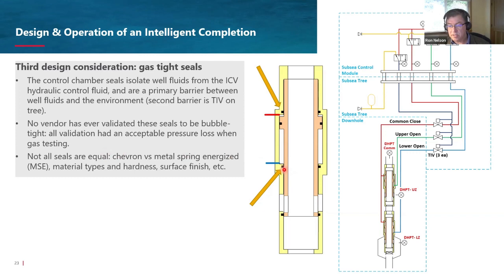And I will say I did some testing on an ICV last April, and we did demonstrate that at least the seals we were looking at were gas tight, but they're also, in my opinion, probably the best seals in the industry. There are other seals out there that aren't nearly as good as the ones that we tested. So when you're looking at your ICVs for your application, spend a lot of time looking at these seals, ask about how they've been qualified, and understand their design and make sure you're happy with them for your application. Because there is a lot of evidence in industry that these seals are leaking on at least some wells around the world. I know Petrobras, for one, have had a lot of issues with these in some of their wells.